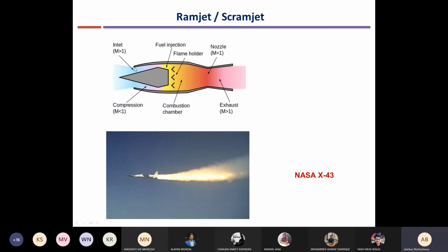Okay, so if you are at supersonic speed, the area needs to decrease for a diffuser, which is counterintuitive. Based on our common day-to-day activities, we always feel that when the area is decreasing, the speed increases. But at supersonic speed, the opposite behavior is true. If the area increases, the speed increases. If the area decreases, the speed decreases.